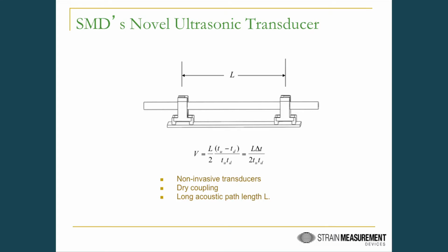It doesn't require any acoustic gel, and it also allows us to make a virtually infinitely long acoustic path length. As long as we have enough power to send the pulse that far down the tube, we can make the L much longer. So you'll see in a minute the kind of accuracy results that we've been getting.